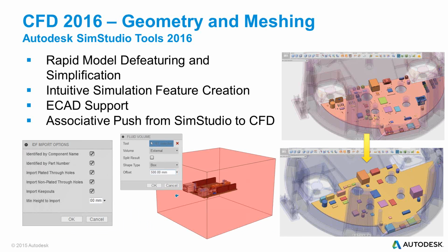There's also the ability to do add-in apps. One of the things we're adding shortly is ECAD support, so IDF import, and this little graphic shows what that user interface is potentially going to look like. Making fluid volumes, you can do that in CFD today, but it has a limit, and so there's added functionality that SimStudio Tools will add. And again, this is an associative push from SimStudio to CFD, much like you'd have with Inventor or SolidWorks or Pro/E or any of the other CAD tools.